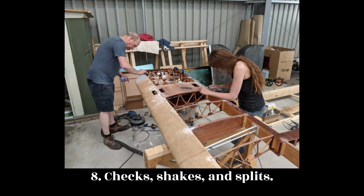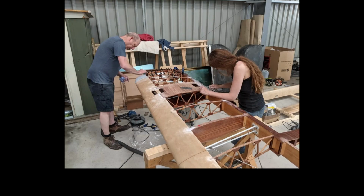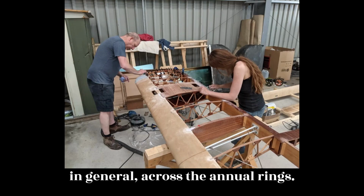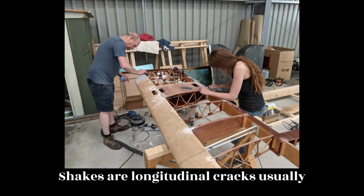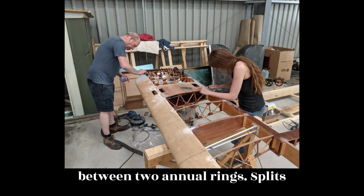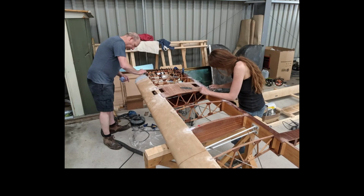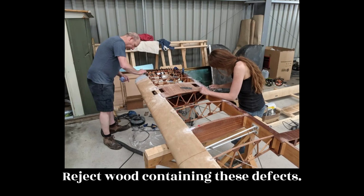8. Checks, shakes, and splits. Checks are longitudinal cracks extending, in general, across the annual rings. Shakes are longitudinal cracks usually between two annual rings. Splits are longitudinal cracks caused by artificially induced stress. Reject wood containing these defects.